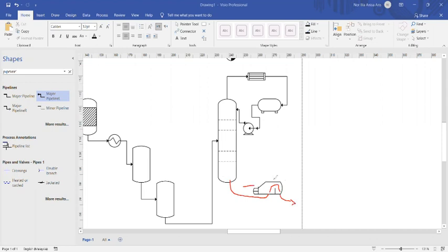So steam will be inserted here and then go outside here. So it will recirculate the heating medium, maybe you use steam or you use hot water, depending on the temperature you control here. So from the tower, it will enter this area, and to ensure that we supply enough fluid from the bottom part, it should pass the weir part here. So let me clear the drawing first.